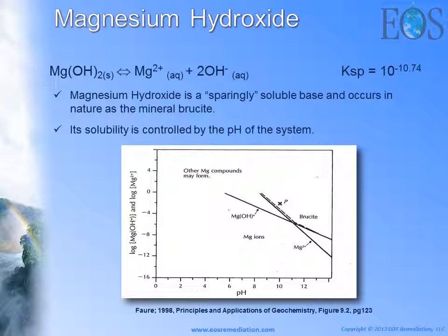In a groundwater system, as you get up gradient to down gradient flow of acidic groundwater, you essentially have this nice long-lasting effect where the pH of that groundwater is shifted to an alkaline condition as it comes into contact with the magnesium hydroxide. The magnesium hydroxide will be able to reprecipitate in the location that it was injected into, and then as the groundwater flows out and more acidic water moves in, it's there all over again. So you get this continuous cycle. Magnesium hydroxide has an extensive life in the subsurface, fantastic longevity, and a strong ability to regulate and control the pH of a system.